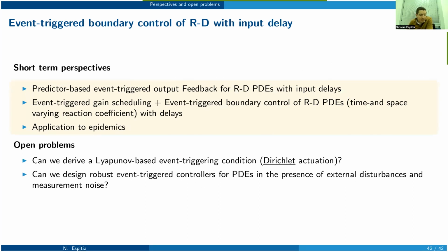So of course, the next step is to study event-triggered output feedback for reaction diffusion PDEs with input delays. This calls for an observer-based design.